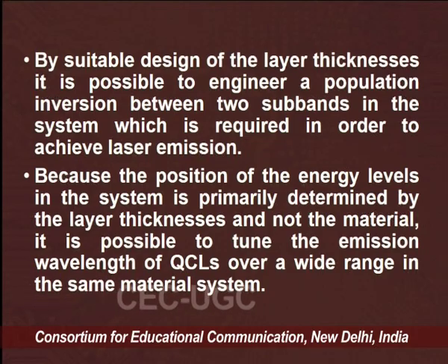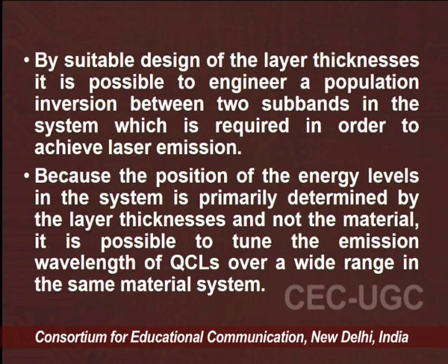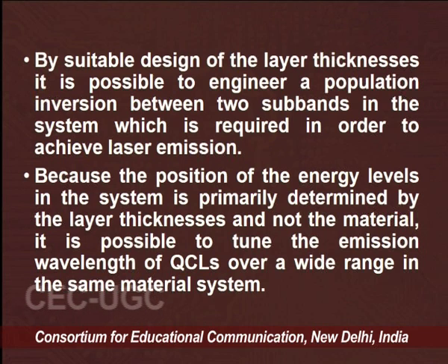The basic requirement of lasing action is population inversion. So, to achieve laser emission, there is a requirement of population inversion between the two subbands in the system. Because the position of the energy bands in the system is primarily determined by the layer thickness and not the material, it is possible to tune the emission wavelength of the QCL over a wide range in the same material system by layering different materials or by layering various thicknesses of the material.